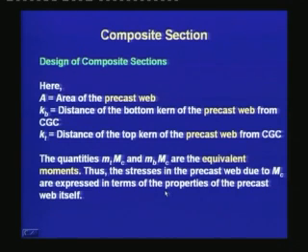The whole purpose of defining the equivalent moment is to have an expression of the stresses in the precast web which involves the properties of the precast web only. The properties of the composite section have already gone into the definitions of the ratios mt and mb.